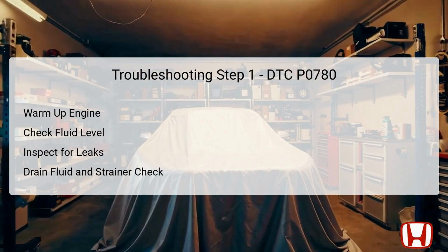Following these checks, the next action is to drain the transmission fluid through the strainer, which serves to filter out any metallic debris or excessive clutch material. Investigating the strainer for such debris can provide insights into potential internal wear or damage within the transmission, guiding further troubleshooting efforts.